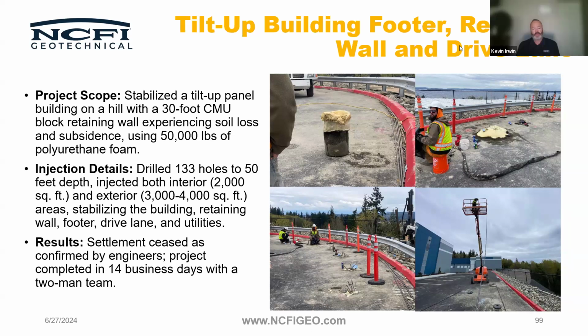Even in that circumstance, if I were doing a grout curtain with dual component foam, I'd still be injecting top down and looking for my bump at the surface. I'd be monitoring, because that does prove to me that in that general area, I've made the path of least resistance, filled all the other paths of least resistance until the last path of least resistance is up.